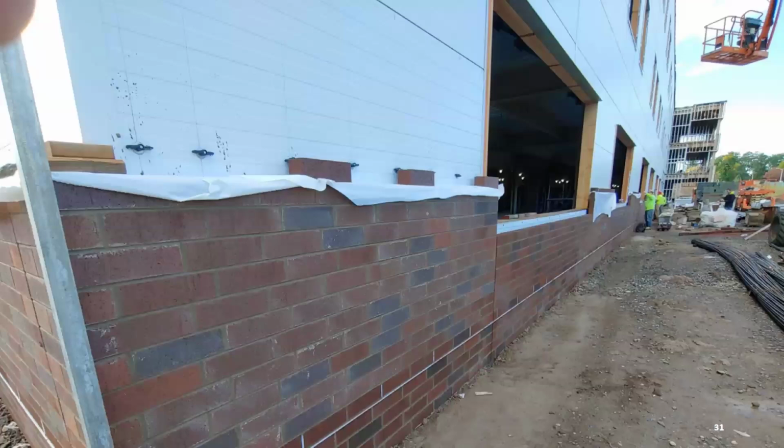Here's an example of a project. This is Colonial Middle School in Plymouth Meeting, Pennsylvania. The entire building was cladded with insulated metal panels that went around on all sides. This was an entire barrier backup system. One of the benefits of the barrier backup system, besides being able to dry the building in quickly with the insulated metal panel acting as your vapor and air barriers and your thermal performance there, and also your weather tight barrier, from there you can add those architectural elements.